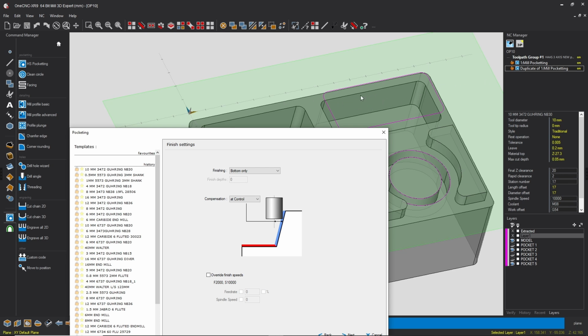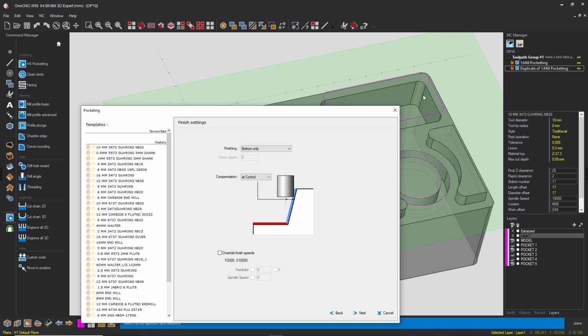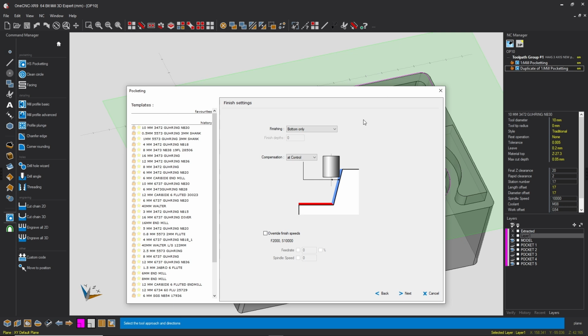So when it comes onto this wall, it's going to have a number of -10. It will arc on to Y -10, feed round, and say this was 80, it'd be 85 on your code. So it is sort of roughing it and then finishing it, but it's not using comp. It's just offsetting the tool.